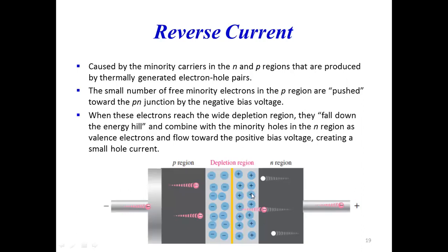You are getting more and more electrical charge at the depletion region, and because of this very heavy electrical potential, the minority carriers which are moving get accelerated. Because of their acceleration, those minority electrons will knock out a few electrons from the other covalent bonds. So what will happen? More and more electrons will be present in the circuit.